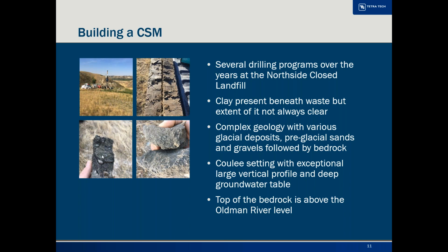It's really dark because there's lots of shale particles in. You can see there's pebbles in it, but it's a very tight material. This is hydraulic conductivity 10 to the minus 10. However, there is of course issues with fractures in these till materials. So some of the permeability is not clearly defined. And underneath there is the Old Man Formation bedrock.